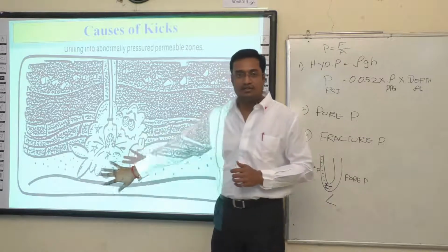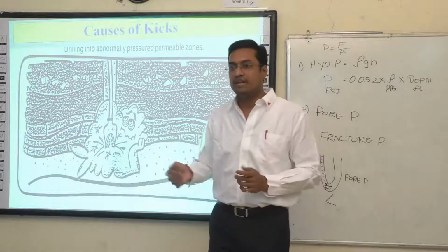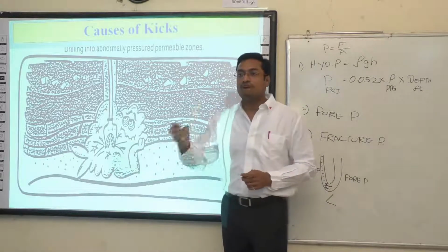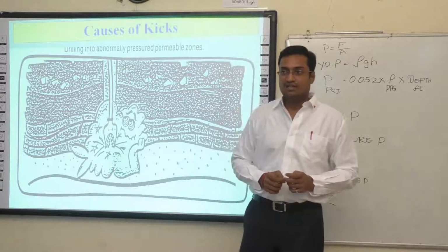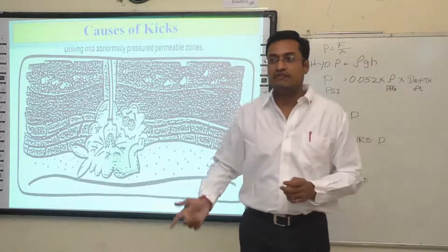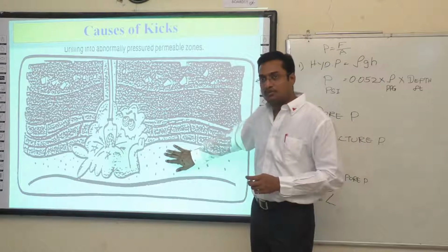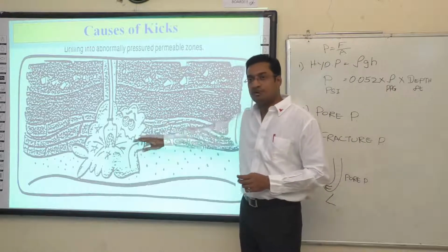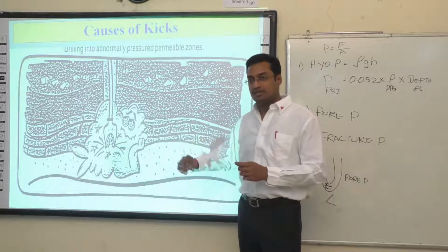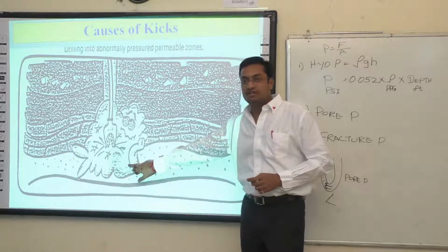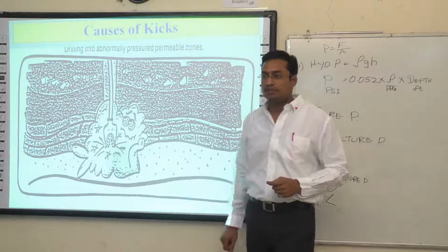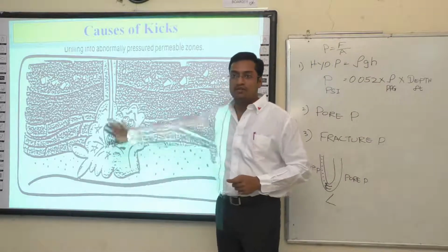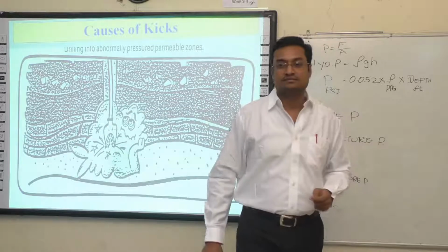It is not that you're going to increase your mud weight or going to do any well control measures. No. When you start drilling, you keep looking for the indications. If you start getting indications, that means you have entered the overpressure zone. If you are careless or if you have lost control of your depth, miscalculation, so you enter into the formation without knowing. And if you drill faster, automatically you will get into a kick situation.